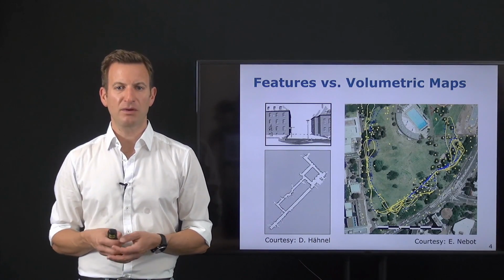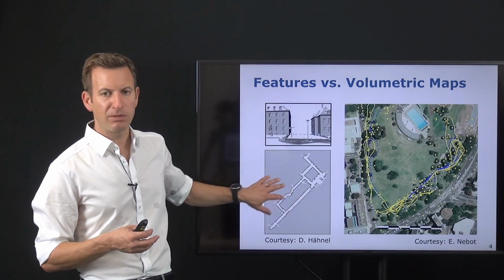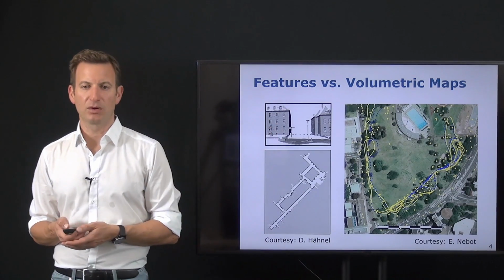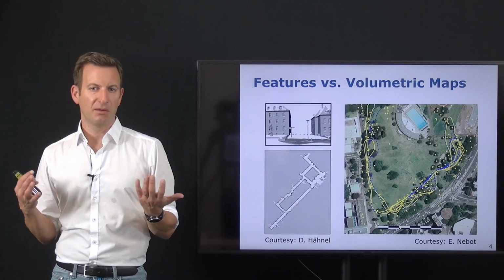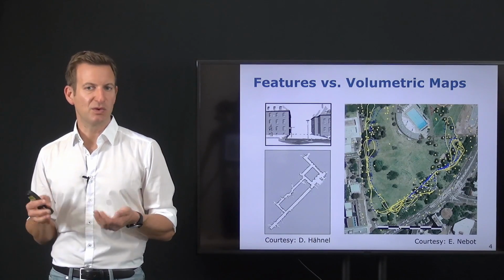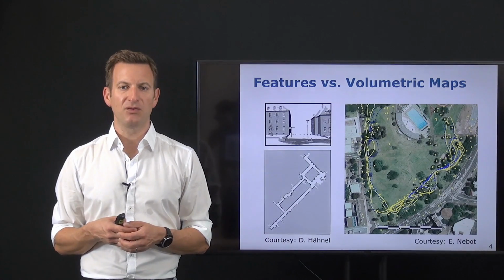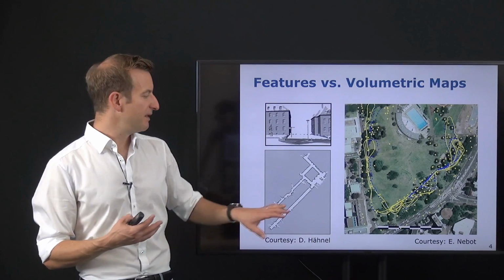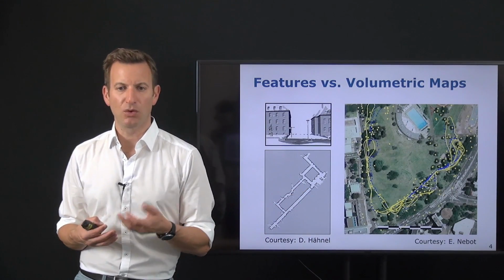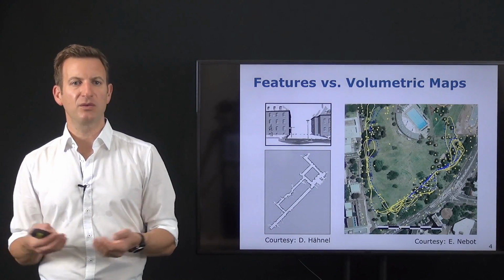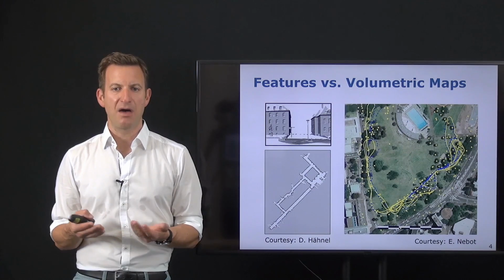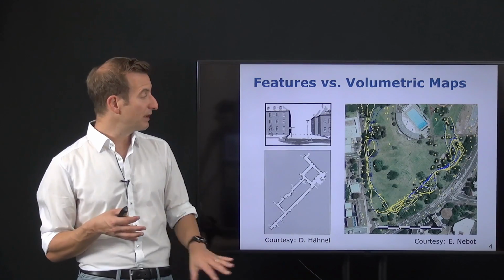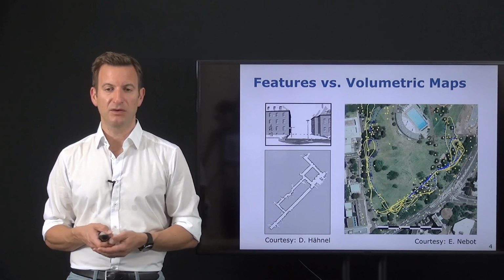We will look into volumetric representations. This can be in 2D, this type of floor plan map that we see over here, or we could even extend it to 3D and then store a full volumetric model of the environment. They are both different types of representations, and we can use both, for example, for localizing a robot in the environment. Given that we often want to plan a path through the environment, I feel that this occupancy grid-based representation is more suited because it explicitly represents free space, and we can use it to plan a path through the free space, and therefore it is preferable in several applications. So today we will be looking into these types of occupancy grid maps.